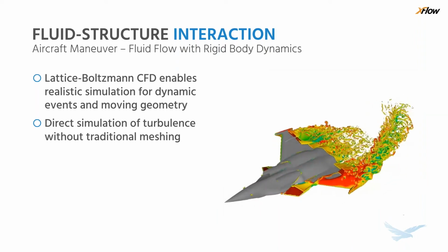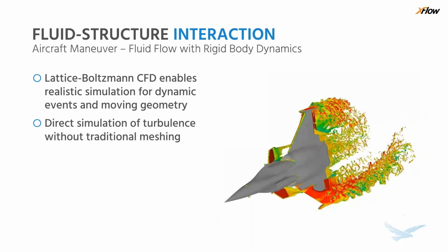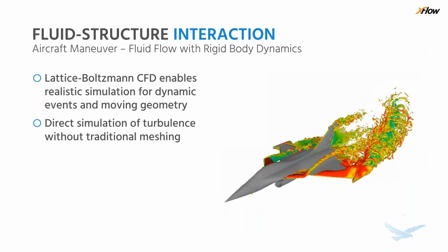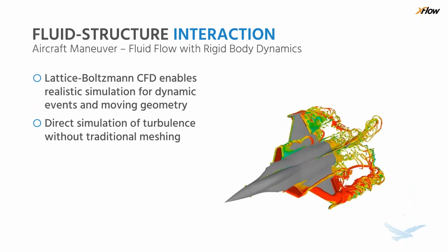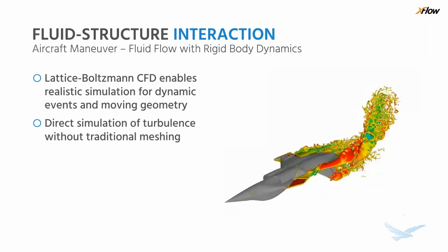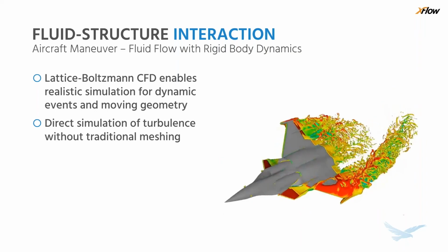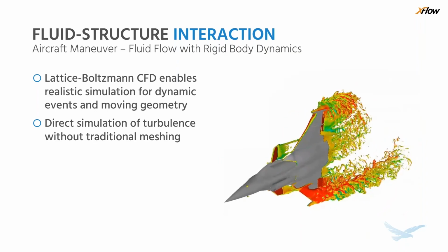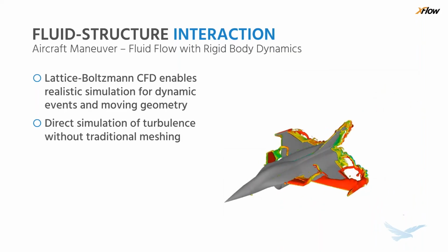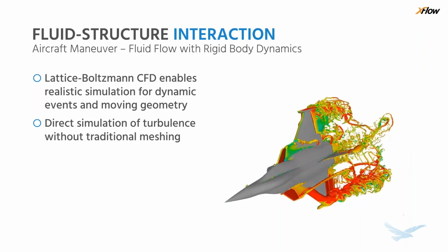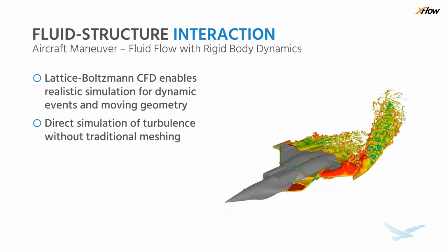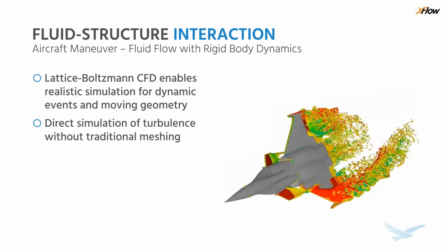And built into XFlow, you can also include the rigid body dynamics. Those of you that might be using SOLIDWORKS Flow Simulation right now will know that that's a limitation of that software, is you can't have moving geometry. And so here we can see how the fluid interacts with a moving piece of solid geometry, and we've got that structural interaction, and it's all done within the XFlow tool. And so this is a case where the fluid is more important than the structure to us.